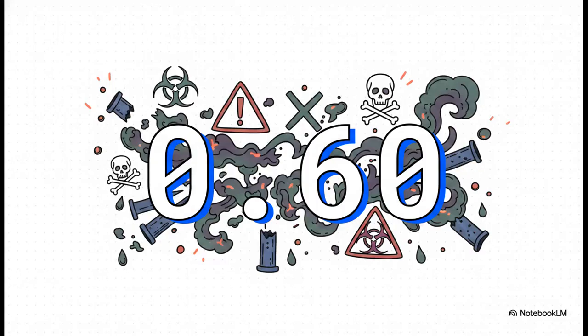Now, look closely at this specific penalty factor, 0.60. On the index we were just talking about, this penalty is assigned specifically for toxic materials. What's absolutely crucial to understand here is that toxicity isn't just about health and safety exposure. It's actually a mathematical multiplier for disaster probability. Think about it. If a pipe bursts and the material inside is highly toxic, the emergency response is instantly complicated, right? It makes an explosion or a fire far, far more likely to spiral completely out of control.